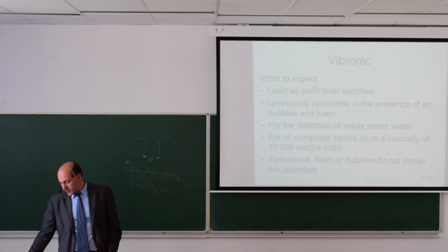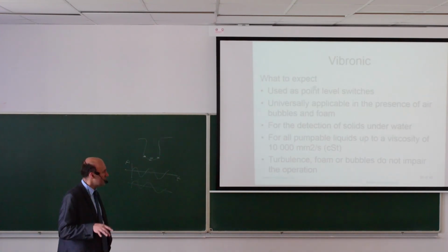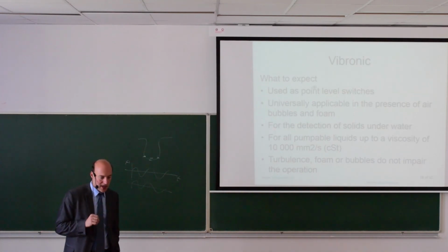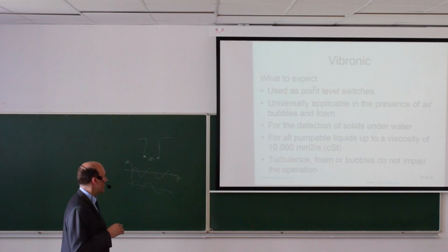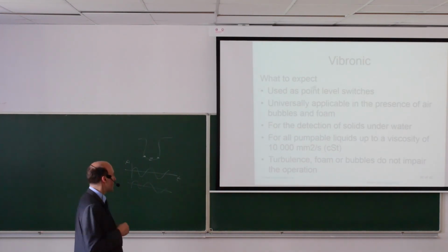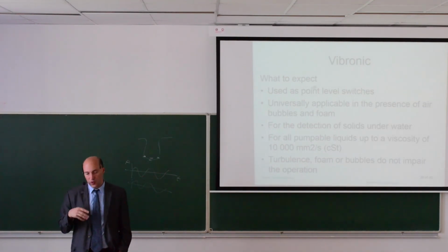So the vibronic sensor is only point level, so it does not give you continuous information. It's only yes or no, tank is full, tank is empty. It is not affected by foams or bubbles. It can work also as a detector for solids underwater.